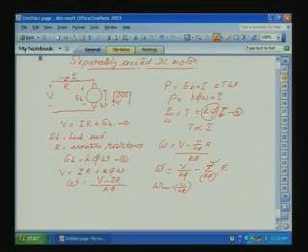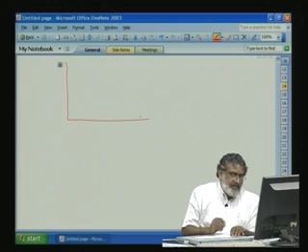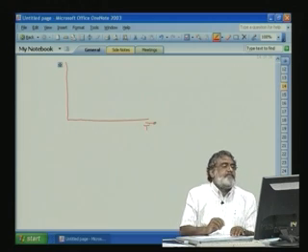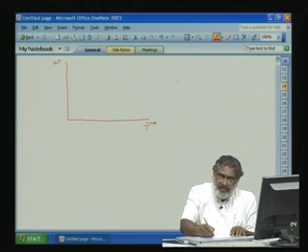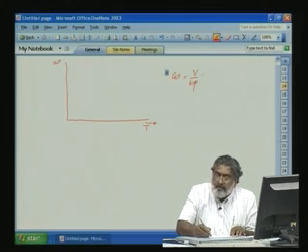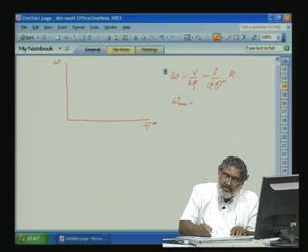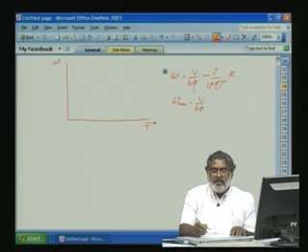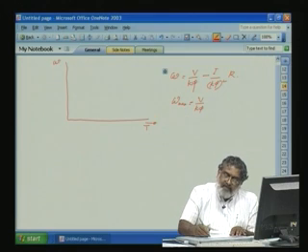Okay. Now, from this one, how will we get the torque speed characteristic? Let us see. This is our torque and this is our omega. Now, from the previous equation, we will write the equation again here for our reference. Omega is equal to V by K phi minus I divided by K phi square into R, and omega maximum is equal to V by K phi. So, the maximum speed, for no load with I equal to 0, is proportional to V, V by K phi.